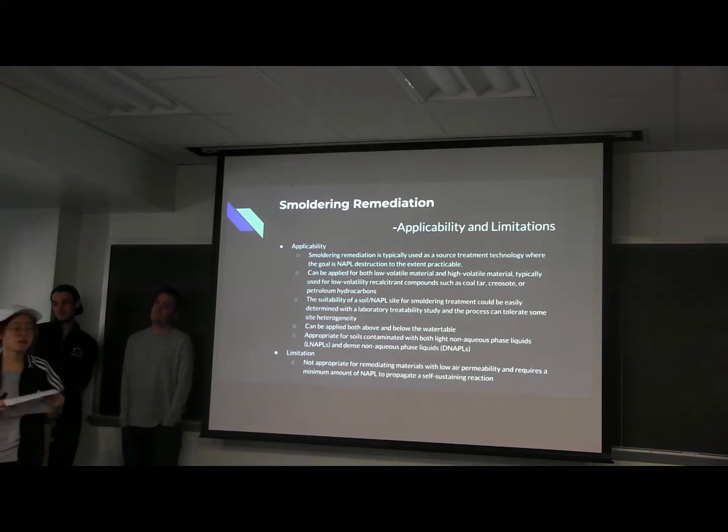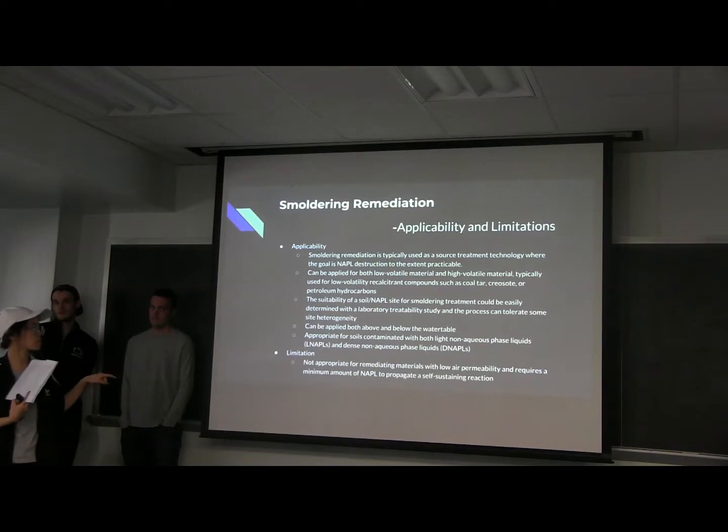But just like I mentioned before, smoldering remediation is not appropriate for remediating materials with low air permeability, and it requires a minimum amount of non-aqueous phase liquid to propagate the self-sustained reaction.